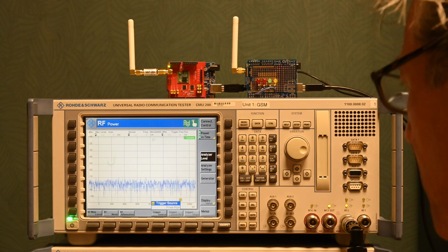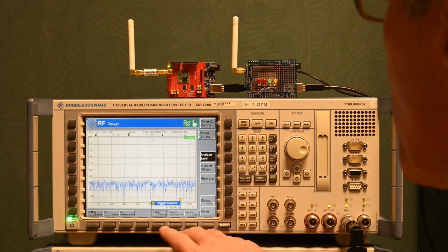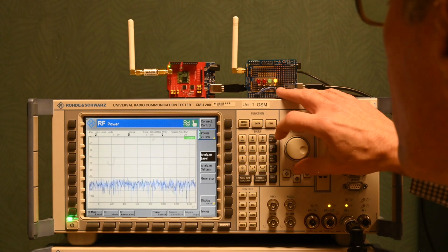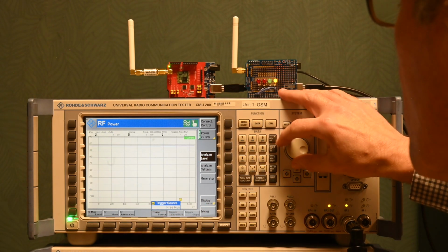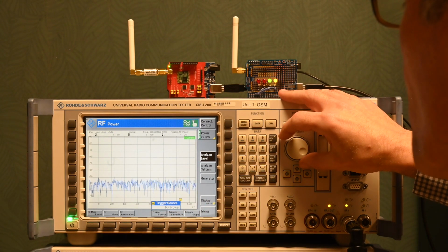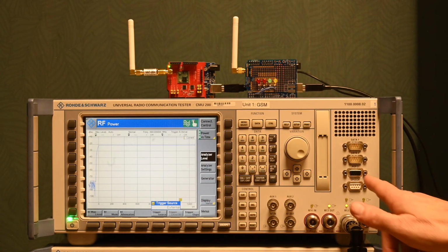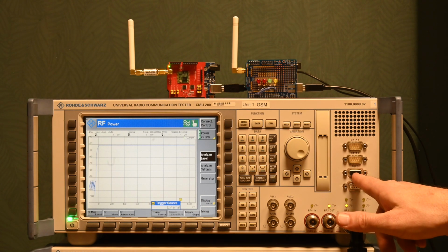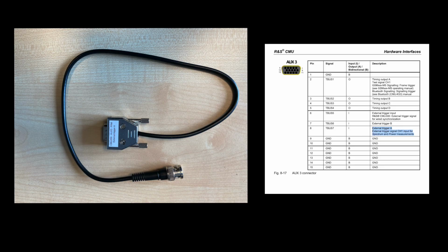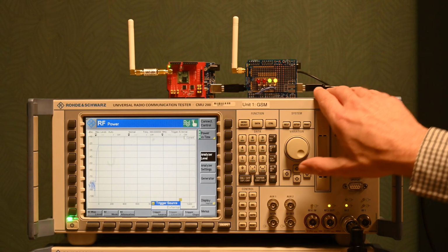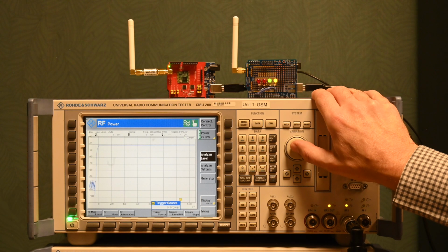Now we see the device is triggering on free run, and we got a couple of trigger options here, which is also on RF power, IF power and external. And the external part, that comes in via the aux port here on the front, and I made a little adapter cable to make it a little bit easier to connect to stuff. But right now I will be using the IF power here.